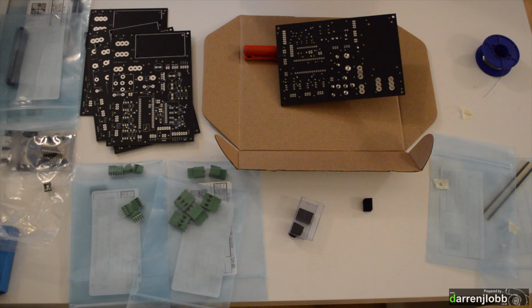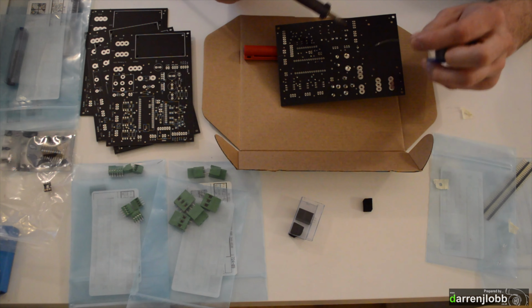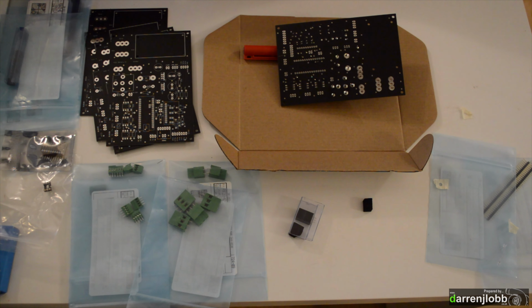If I was doing this again, a little bit of advice: you want to do those before the caps. In fact, you want to do those big tall caps last. It just makes it easier. If you do the short stuff first and the tall stuff last, everything kind of holds itself in when you turn it upside down. But if you don't, just use something to prop it in. Not a big problem.